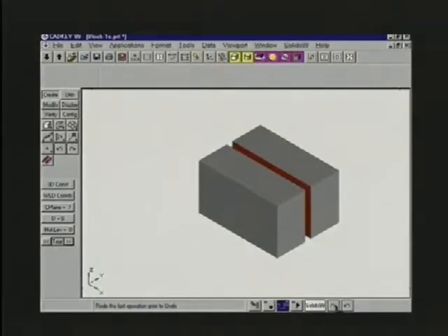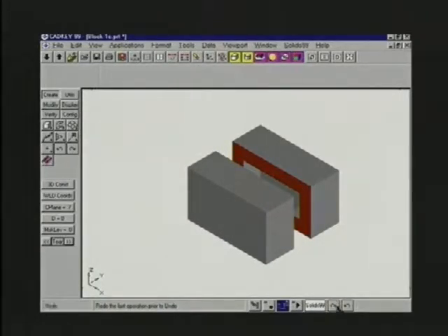Describing the shape of objects in engineering drawings, we have a way to deal with hidden features, and that is we use dashed lines. But sometimes there are objects that have so many hidden lines or dashed lines that it becomes very confusing and very difficult to understand. So we have a practice that has evolved called making section views.